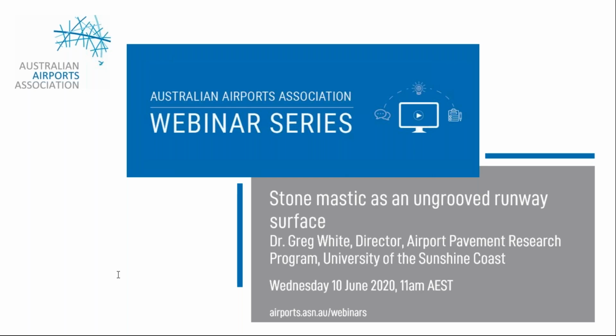Yeah, so I think that what's driving China and Europe, I would imagine as well, to put thick, dense graded asphalt under their stone mastic is just their approach to pavement design. So even if they had dense graded surfaces with grooves, they would still have lots of ungrooved, dense graded mix below it. So I don't think that the pavement structure necessarily needs to change, although I do think that a second layer of asphalt underneath the SMA would make a lot of sense.